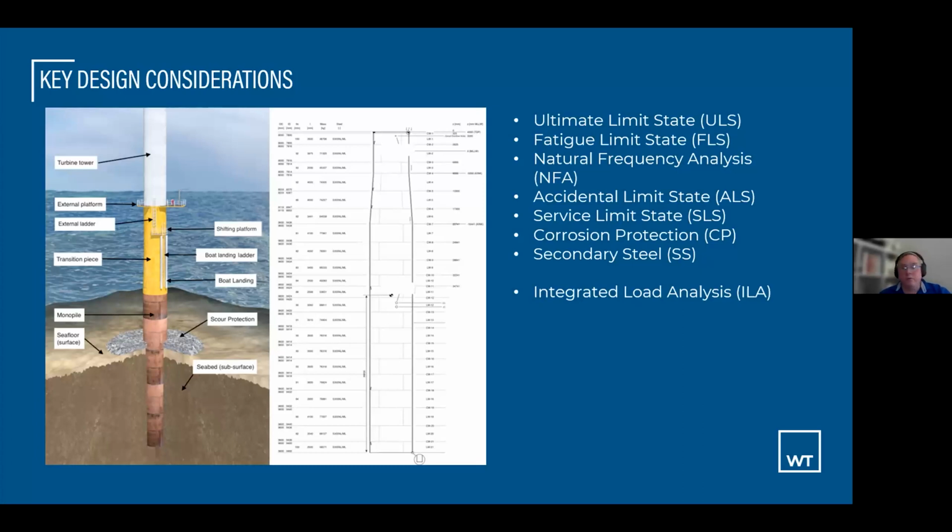To do that, of course, you have to analyze all of your wind conditions and storm conditions to understand what you expect for fatigue. So we will build into this. We expect the 50-year storm to occur twice in the life of the project as the conservative analysis. We have to design to a fatigue limit factor of 3. So you're designing for 3 times the fatigue that you actually think it will see. And that's what drives a lot of the steel considerations.